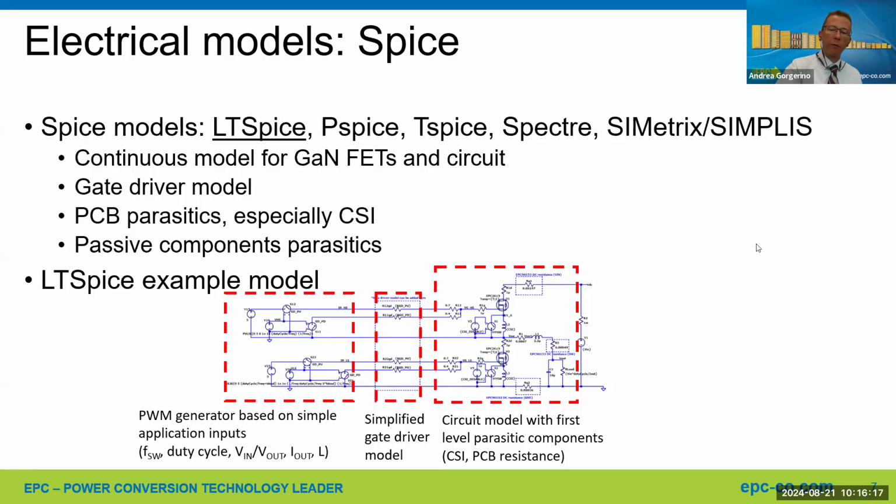And finally, we have this loss analysis via the .meas directive, which basically allows you to get automatically all the details that we got in the previous tools. So the split between switching loss and conduction loss, the turn-on, turn-off. This will also calculate rise and fall times automatically for you, and dV/dt, all without actually doing any measurements. It's in the log file, you just run it and go from there.